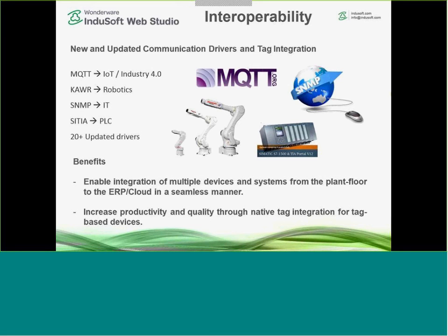We have released recently, and it will be included in Service Pack 1, a native driver for SNMP, Simple Network Management Protocol. It's an IT protocol supported by several devices like printers, switches, and routers. Now from InduSoft Web Studio, we have a native communication driver which allows you to very easily read and write OID values and even receive traps from those devices.